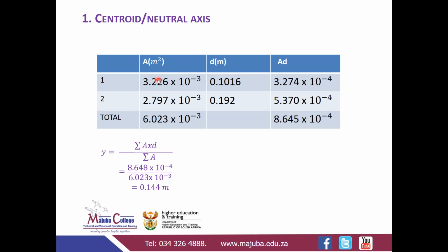All right, so because a plate is a rectangular form, we've seen a rectangular form, you will say BD to the power 3 over 12. Make sure that your values are in meters. Okay, don't convert after you've calculated your inertia, but rather put your values in the formula in meters already. Okay, so that's how you calculate the inertia if you are given a plate. Again, it's going to be what? BD cube over 12. That formula that you learn from N5. That's how you do it.